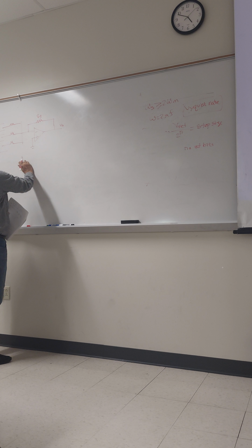This 0.2 volt is actually noise, but we can add it. That portion is known as dithering. Dithering adds a small amount of controlled noise to the input signal before quantization. This noise helps to randomize the quantization error, making it less noticeable and reducing the potential for harmonic distortion.